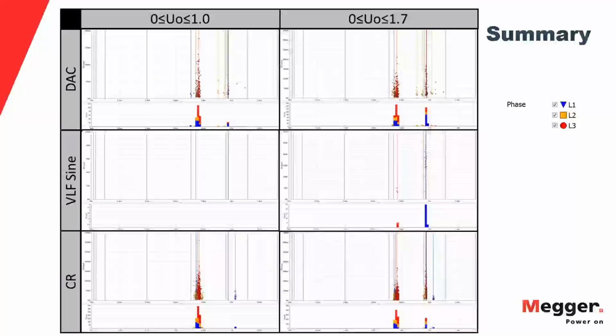We bring our own power supply, so we have control over it. We can isolate that cable, apply whatever voltage we choose, and find out the inception and extinction voltage, which, as you saw in this presentation, makes a big difference in the type of corrective action we might choose to take. So, very good question. We can't do this type of testing with online technologies.